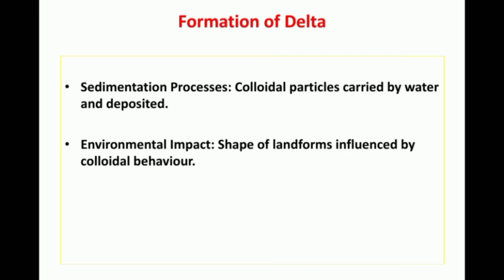As is to be expected, river water contains colloidal particles of sand and clay which are negatively charged. On the other hand, salty sea water contains a number of positive ions. When the water of the river comes in contact with the water of the sea, the negative charge on the colloidal clay particles present in the river water gets neutralized by the positively charged ions present in the sea, because of which they get coagulated and deposit at the site.